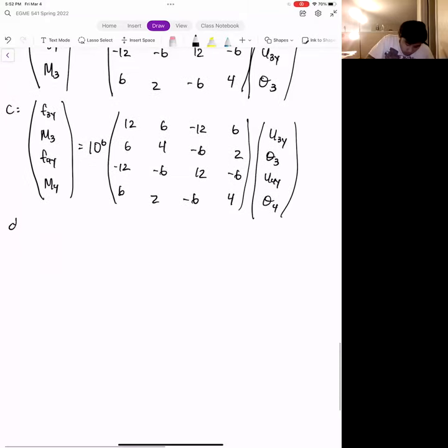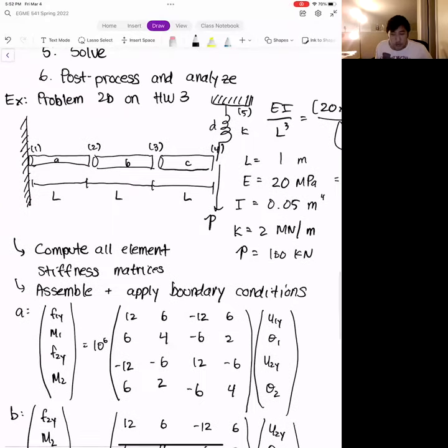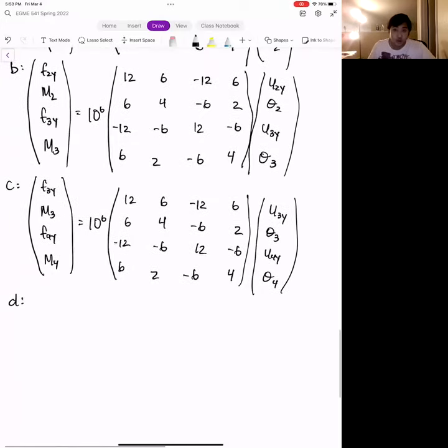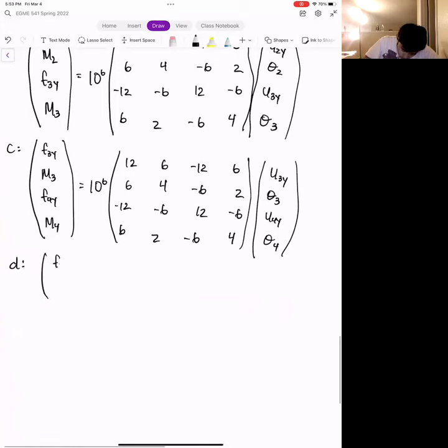Now let's go to the spring. For the spring element stiffness matrix, you can see here it is connected to nodes 4 and 5. But remember, springs can't rotate, so the spring is not going to contribute anything to the rotational degrees of freedom of the beams. The only thing the spring contributes to is the two Cartesian deformations, which are F4y and F5y.